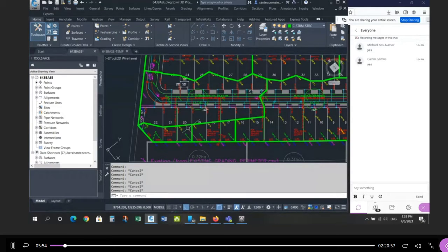In this case too, when I draw them, I can also check that I don't exceed the maximum. Remember that calculation we did? What's the maximum area, so that we can always use a 250 pipe at 0.5%. Okay, so the first thing we did was that. The next thing we did was then amalgamate.